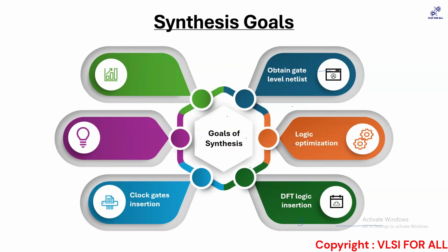You can enable that app option. There is this way to guide the tool, like you can enable the app option stating that, okay, you can do my scan chain reordering when you're doing legalized placement itself, right? During the placement stage also, you can tell the tool, please enable this app option or setting during your placement as well, so that the tool will do the scan chain reordering at that place also. So there is nothing like, if you're doing it in synthesis, you can't do it at PNR. You can enable it at PNR, and it is enabled at your placement while doing your placement activities.